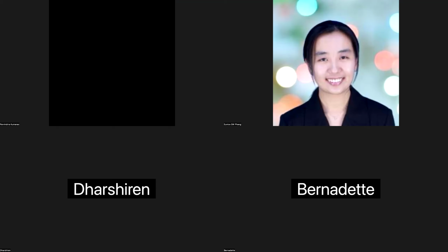Hey, you know what to do, right? Just focus on the cooling system. So you choose your process parameter, you choose the deviations, and then you start working on it. I think there's only one or two parameters here. One of your parameters can be flow rate, the other one is temperature. So for each parameter you choose one or two deviations, and then two causes for each deviation. Then you work from there.